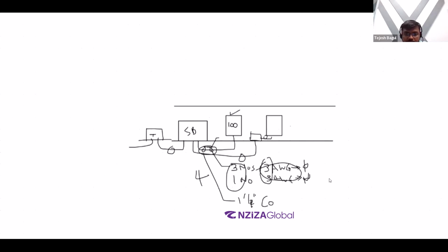Now we'll go ahead and draw another line that will signify the line going into the switchboard. Now let's say this is the switchboard. Just like the transformer, make sure you tag it properly. You can simply copy and paste the same text, or you can use another one. Always try to make sure that you don't have any of the elements overlapped with any other elements. It just gives a bad impression when you are trying to present it to the client.